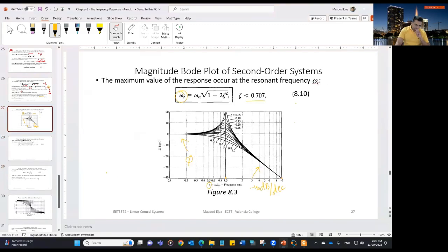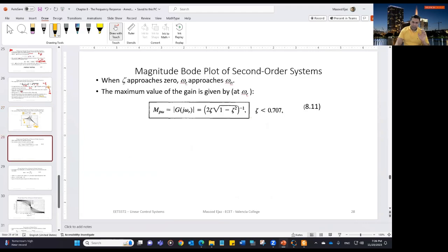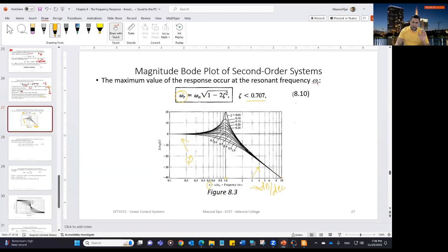So if you have a system with real zeros, real poles and second order poles, then when you're drawing the Bode plot, of course, the real poles we discussed how you're going to draw, the real zero is like a real pole. If you have a second order, then you will incorporate the second order, something like this. And again, you can do approximation. You don't have to be exact if you are doing freehand. Then you can just calculate the peak value using this equation right here, and then based on that peak value, calculate the omega r value.